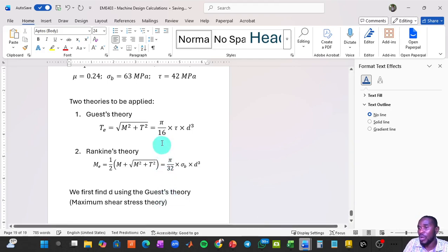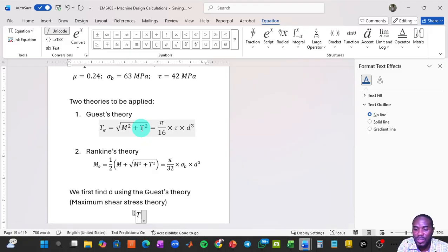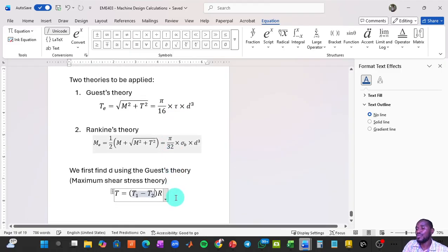So we're about doing that. But the torque here, how do we find it? Now, since we're dealing with belt drives, there was an equation I'd given earlier: that the torque at a particular pulley, that rotates a particular pulley, is given as a product of the difference in the tensions of the tight and the slack sides of the belt multiplied by the radius